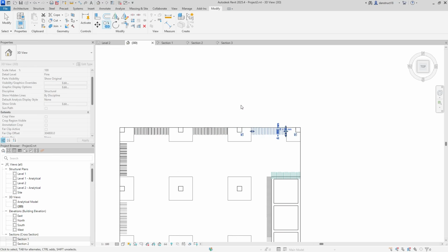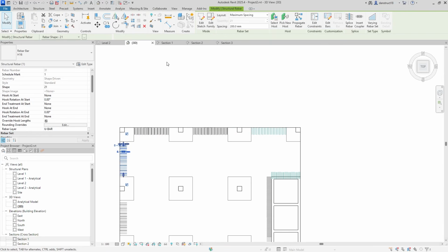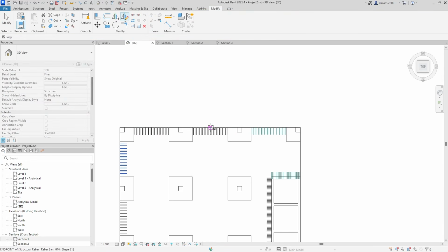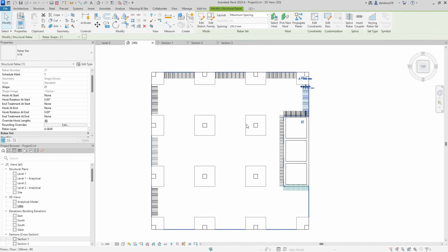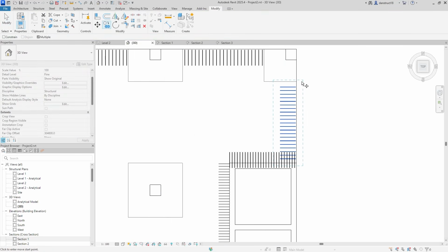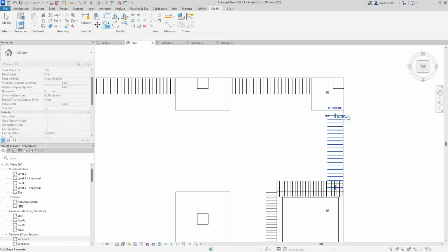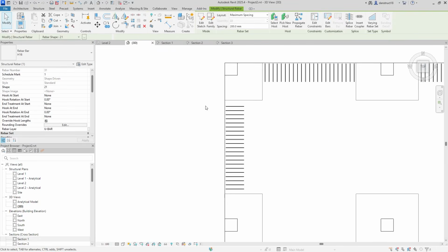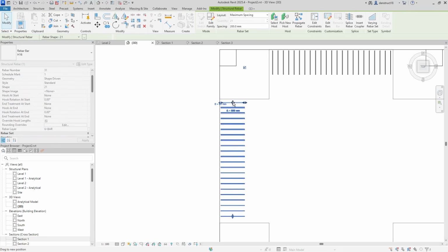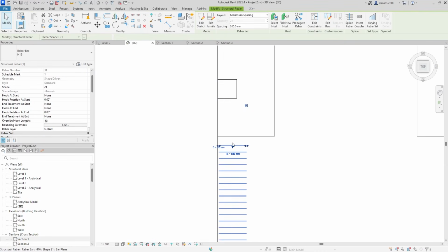All right, good. So I'll select this one here and I'll go ahead and use mirror draw axis, specify the midpoints. There we go. Click here, great. And I'll go ahead and copy this one from this point here, copy. And oops, so this one here, I need it to extend outwards to this point here. I want to check if that's the case here. Okay, so it didn't. All right, so I missed it by just a bit.